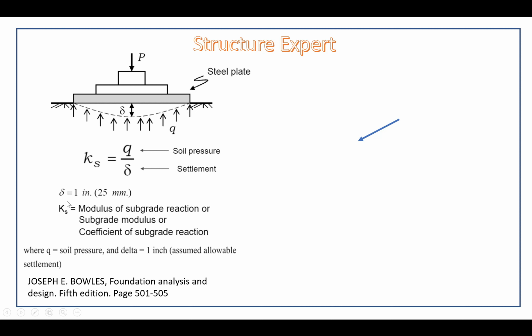In the parameter, Ks is the modulus of subgrade reaction. You see here, this is the modulus of subgrade reaction of soils. We can model it like a spring support at the footing with deformation. So it has a relationship between the deformation and the soil stiffness.